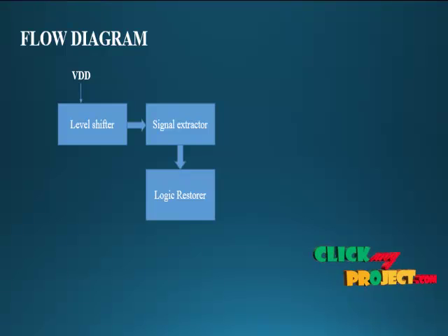The proposed on-chip PLC receiver receives the data superimposed on power lines, and the data such as scan test data are sent from a test instrument. Therefore, the transmitter for the PLC receiver is an external instrument rather than one on the same chip. The receiver was designed in CMOS technology. It consists of three building blocks.